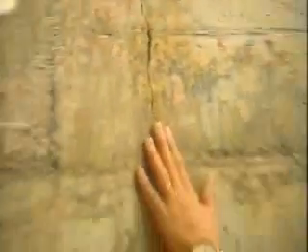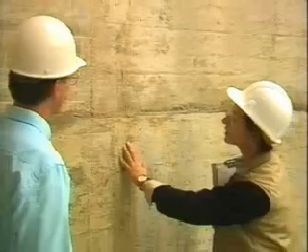As with other features, the downstream face is susceptible to cracking, concrete deterioration, surface defects, and leakage. Let's look at each. Note any cracking that is new, or that is increasing in length, width, or displacement. If you have doubts about whether a crack is significant, check with an experienced inspector.